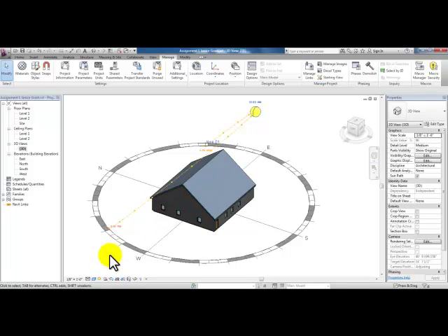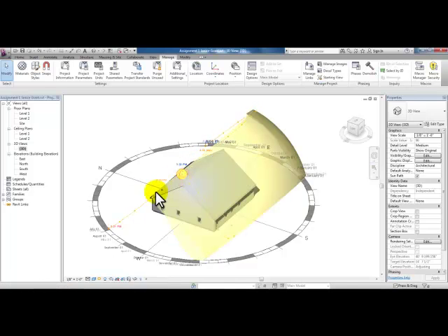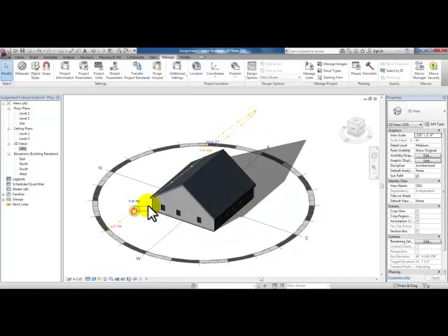You'll see the sun path at a specific date and time, and then the next icon next to the sun are the shadows. The shadows are off right now, so go ahead and click on that little icon. It looks like a ball with the shadow underneath it, and it'll turn the shadows on. You can change the date and drag this ball at different locations to see the different shadows. Holding your left mouse button down to drag this ball into different locations. We'll be taking a look at this with more detail as we work with our assignments.